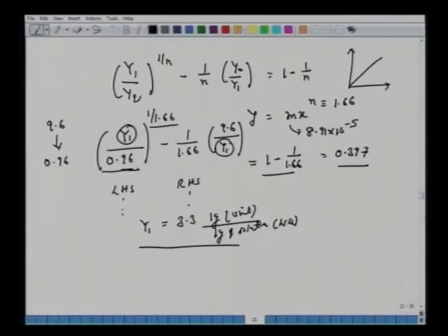So again, let's quickly draw the schematics. We have stages 1 and 2, this is X1 and this is Y1, this is Y2 and this is X2, and X0 is 0, and here we have Y0. So Y0 to Y1 and Y1 to Y2. Y1 and X1 are in equilibrium, Y2 and X2 are in equilibrium. LS is known to us. We want to find out GS1 and GS2.